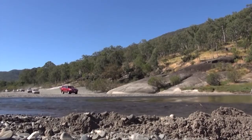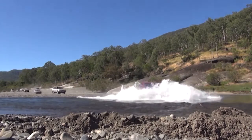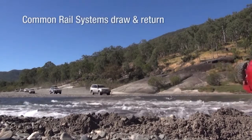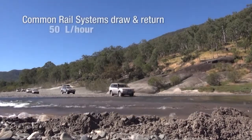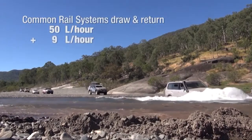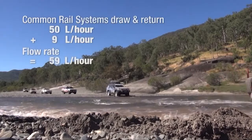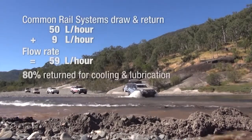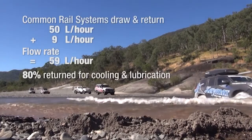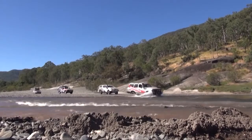How do we stop our vehicle getting water in the fuel system? We have really high flow rates. Common rail draws from the tank and returns in the vicinity of 40-50 litres an hour, and another 8-9 litres which is used. So we have a flow rate of 50-60 litres an hour through the system. 80% of this is going back for cooling and lubrication of the components. So when we get water in it, it quite rapidly is carried through the system.